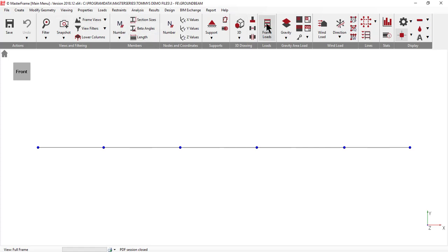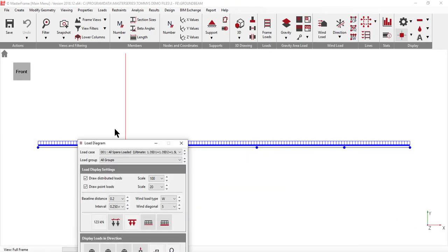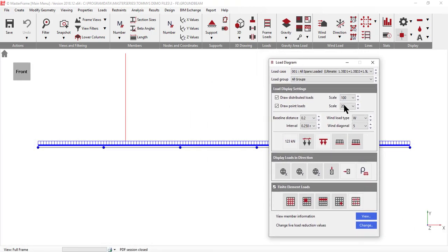Now if we look at our loading, we'll see that we basically have a continuous load except for this one point load. And if I draw some values on that for you, you'll see it's slightly big, plus the 36 kilonewtons per meter run on the loading on the continuous beam. So simple continuous beam. But the one trick that you need to know when doing concrete beams is to do with load patterning. Because this is continuous, we need to think about our load patterning.